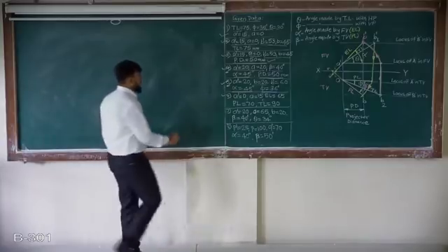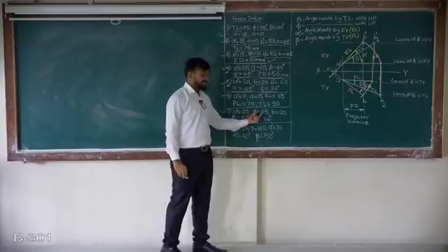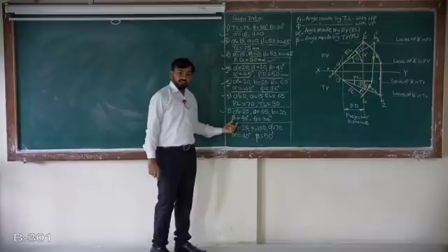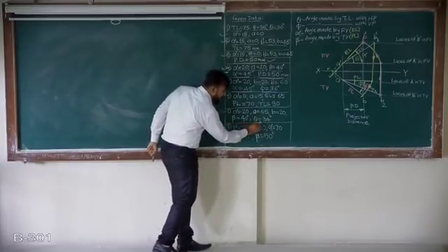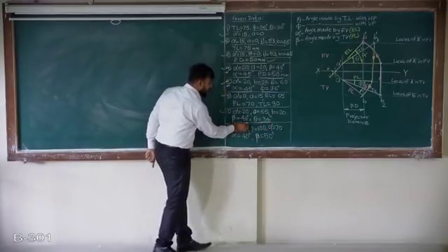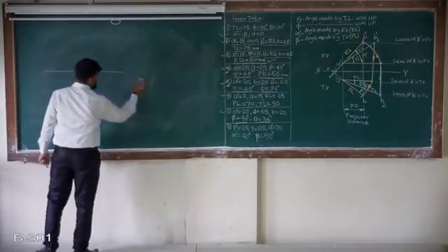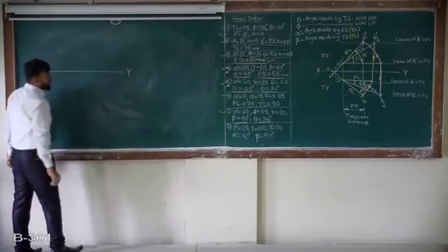Okay, now question number 7. Point A 20 mm above, 65 mm from VP. Point B is 20 mm from VP. Top view makes angle 40 degree with VP, and this is theta, means line is inclined to HP. So line is inclined to HP, that is theta, and top view makes or plan makes angle, that is beta. So 4 parameters, last one is theta as 5th parameter. I will mark on the paper.